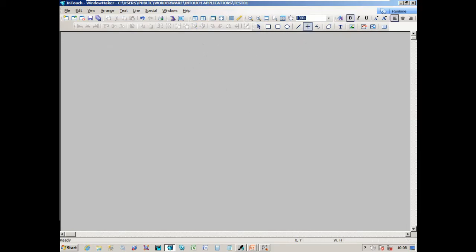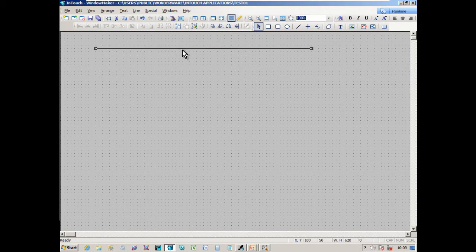I'm going to use this one. If I draw it, literally it's straight every time. If I draw another one, it's always straight. If I move it, see, it can only be vertical or horizontal. So I'm going to make a title bar, and you see now if I click on it, it tells me where it is. It's at 56. So if I want to make that 40, let me put the grid on again, and let me turn it up. Now it's exactly 40.